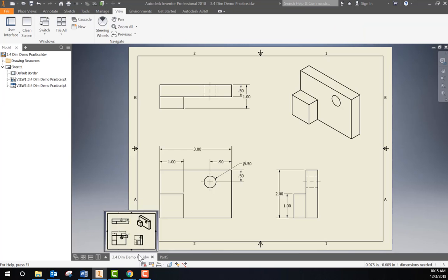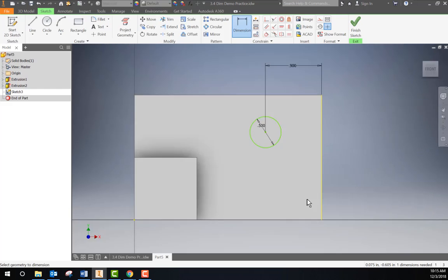And let's look at our drawing one more time. From the center mark to the top edge of the front view, we see that it is 0.5. So we're going to dimension that one as well. I still have dimension selected, so I'm going to choose the center mark of the circle, the top edge, and I'm going to drag over here. Click. I can input my dimension of 0.5 and hit enter. And there we go. We've drawn our circle and we've placed it where we want.